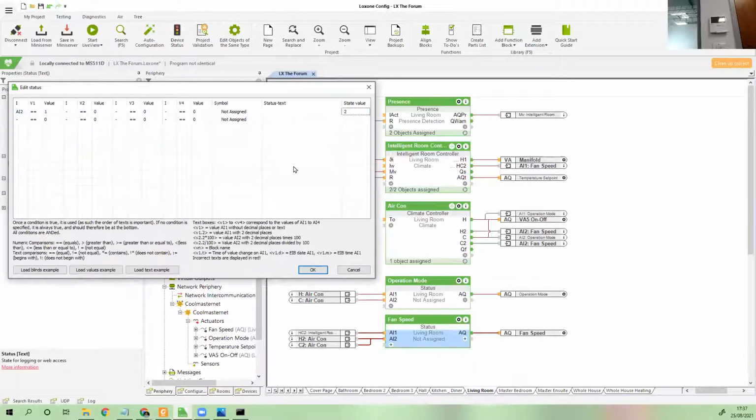Then for the rest of it, we're between 0 and 1. And that is coming from AI1, which is our normal valve actuator output. And whichever scaling you want to use for this is entirely up to you. But I would generally say that if the valve actuator is giving it a value, because remember it's analog, so it's 0 to 10.